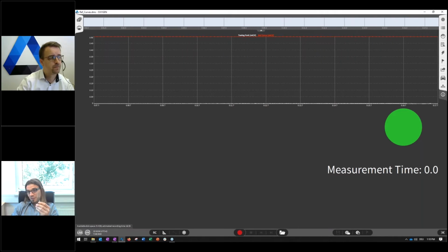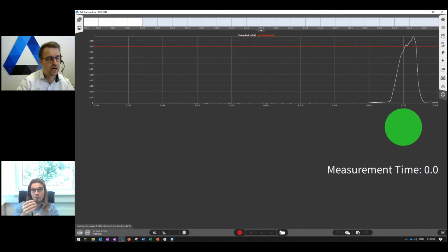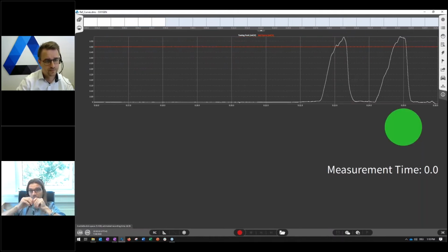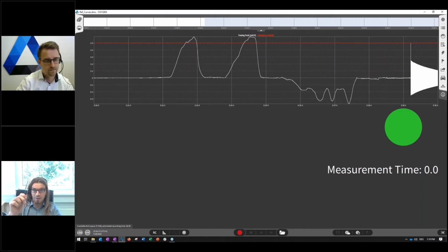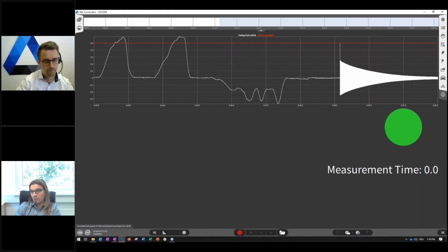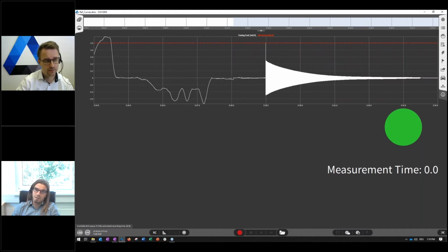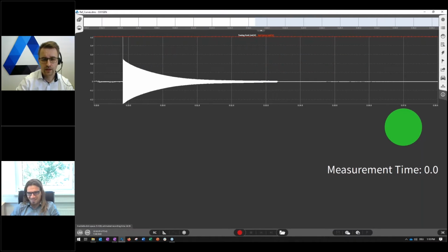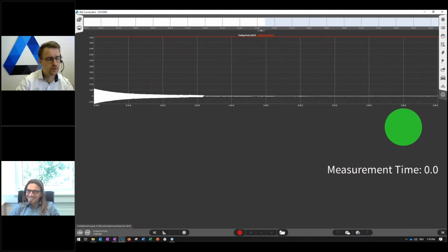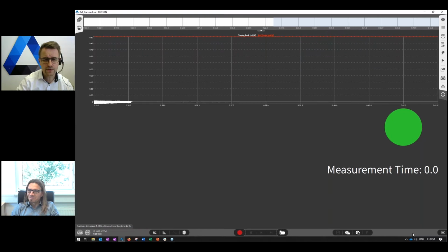That's just a simple tuning fork. And here you have a strain gauge sensor applied. When I press the tuning fork, you see the signal increasing. And when I bend it, you see the negative signal. And now you see the 440 hertz of the tuning fork bending in time domain. Exactly. Okay. Perfect. So this is a live demonstration. Very nice. Sure. Yeah. Let's continue with the next feature.